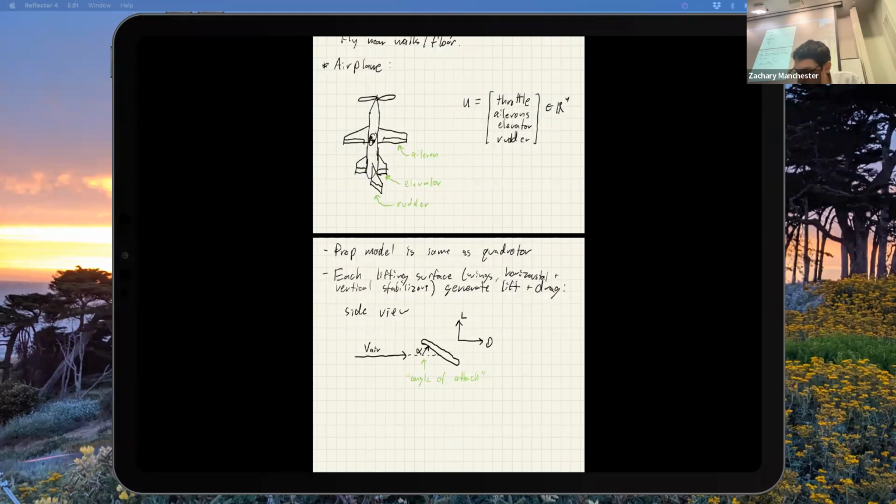This force F is probably something like this, roughly. It's some 2D vector, right? And we're going to decide to write it in these two components, L and D. The specific thing to keep in mind is that this lift and drag frame is called the aero frame. It's associated with the free stream direction. It's not associated with the wing or the airplane. It's the wind frame that we're decomposing into. That messes people up all the time.